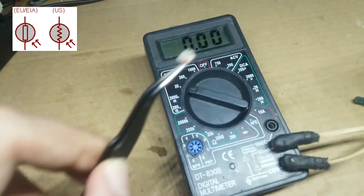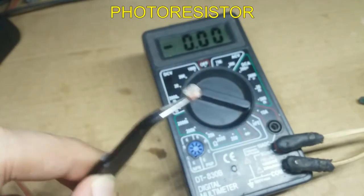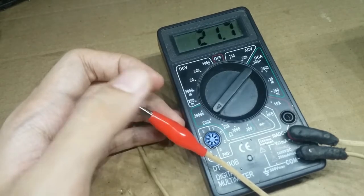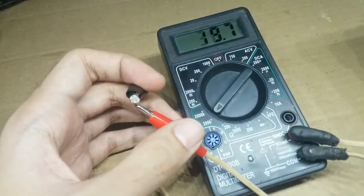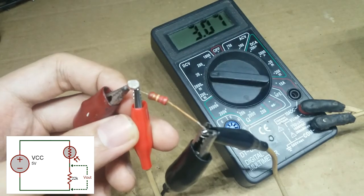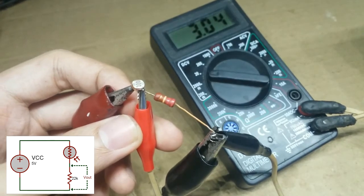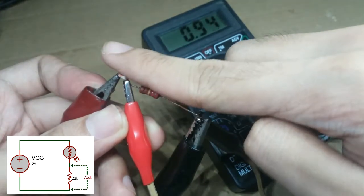This is a light-dependent resistor, aka LDR, or sometimes called photoresistors. The resistance of this resistor is dependent on the light it receives, obviously. When we shine more light, the resistance decreases. So by connecting another resistor like a voltage divider, we now have a changing voltage with respect to the light. Basically, now we have a light sensor.